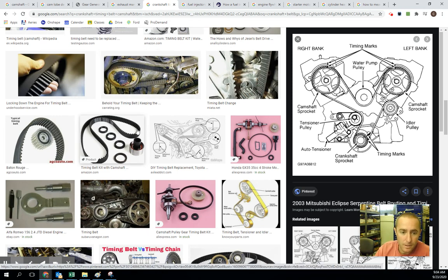You have a timing belt, like you can see over here, and that's going to wrap around there. If you have a timing belt, you typically have a pulley. You can have it geared. If your camshaft was down here, more internal in the motor, you could have a gear connecting this one to your two camshaft gears. You don't see that as much. I think it's a louder setup. It's not as quiet, so you don't see that as much.